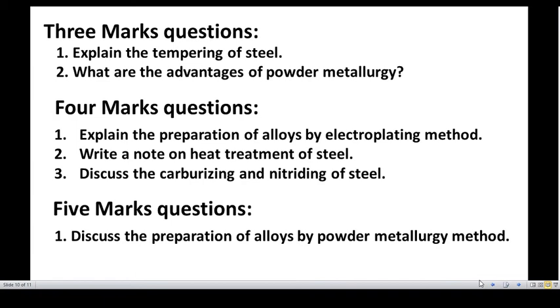Carburizing is also referred to as case hardening, which is a heat treatment process to produce a surface resistant to wear while maintaining toughness and strength of the core. So after carburizing, what happens? After carburizing, the work is either slow cooled for later quench hardening or quenched directly into oil. So this is about the carburizing process.